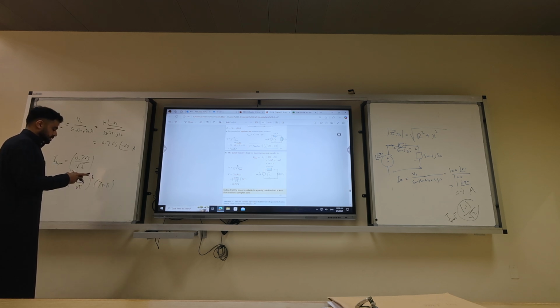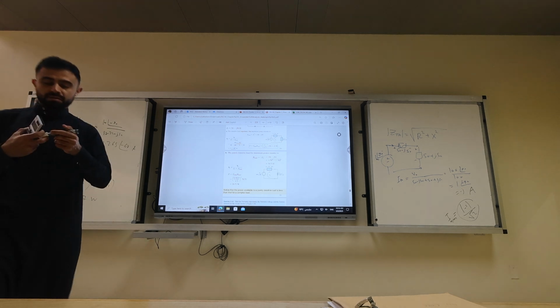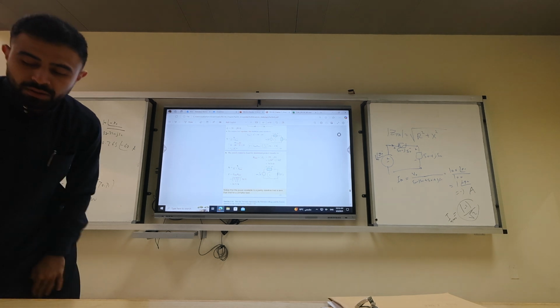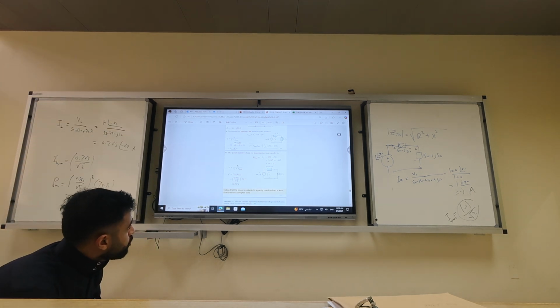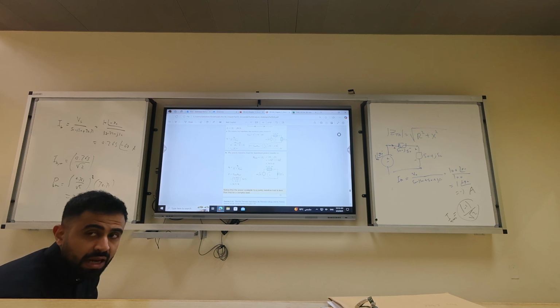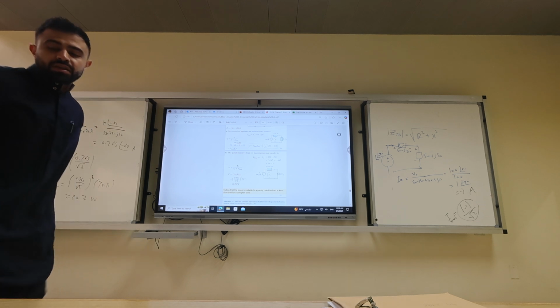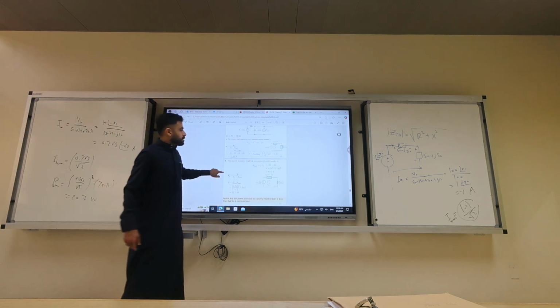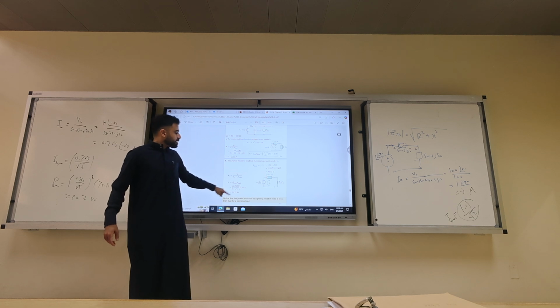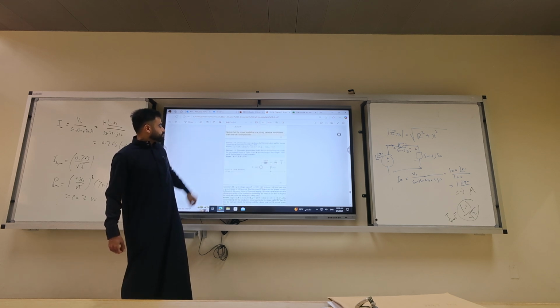So you take this 0.765 divided by square root of 2, squared, times 70.71. It is less power, 20 watts, okay? 20.7. I don't care about the numbers, okay? Because when you have an MCQ, you should be fast enough to figure it out. Get it? So what do you notice? The maximum real power occurs if we connect a complex load or a resistive load? Complex. 25 is bigger than 21.